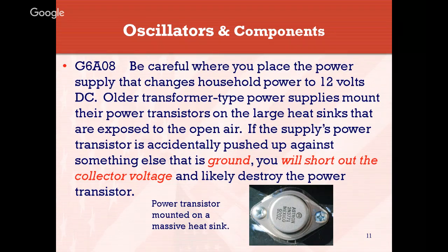If the supply's power transistor is accidentally pushed up against something else that is ground, you will short out the collector voltage and likely destroy the power transistor. So you just got to be very careful of where you put that. You also want to make sure that there's plenty of airflow because those transistors can get very hot and need to be cooled down. It'll extend their life if they don't run too hot.